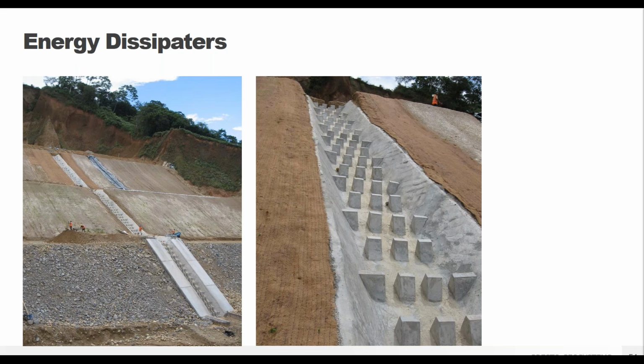They can be placed on both shallow and really steep slopes, same as the GEOWEB panels themselves. Utilizing a tiered channel system like this can also help limit the height and the angle of the channels, which can help with installation concerns while still containing and directing your water downslope. These dissipators were pre-formed off-site and then brought in. They were installed within the cured concrete by doweling in and then providing an epoxy bonding agent.